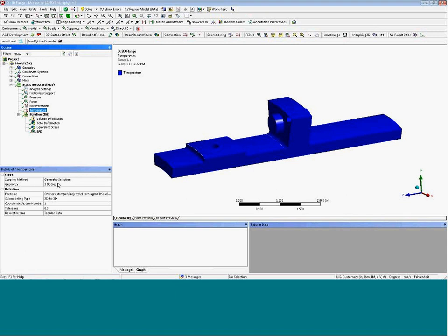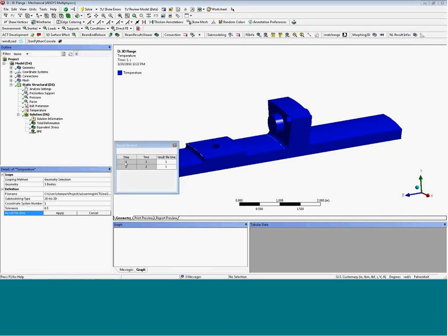extension. Then when we select the bodies that we want to apply this temperature mapping to, we need to give it the result file from the 2D analysis, and say that the submodeling is going to be from 2D to 3D, and then also some tabular information here. So there are 2 load steps in this structural problem. What temperature do we want to map in from the thermal result file? So you can see little tables pop up, different things, little drop downs. There's a lot of things you can do with the extension.